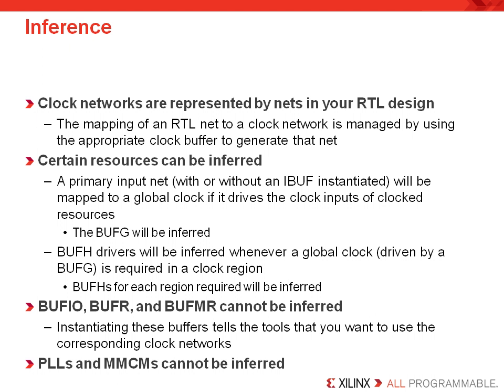These wizards will customize and configure PLLs and DCMs by giving you GUIs to set the proper attributes and include support for driving the output clocks on the appropriate global buffers. Likewise, they help you configure advanced features such as clock division, the use of global buffers, clock feedback, etc. Basically everything we've talked about in these 4 recordings.